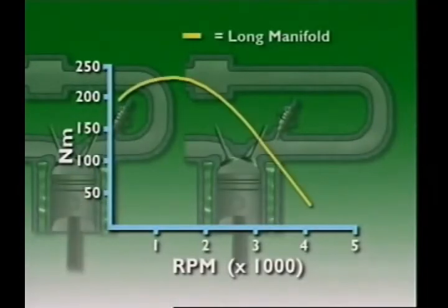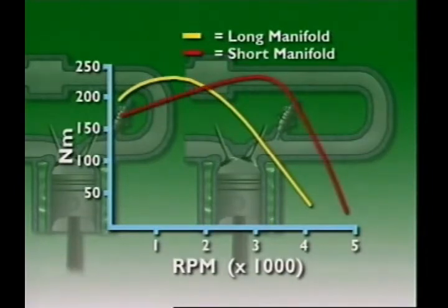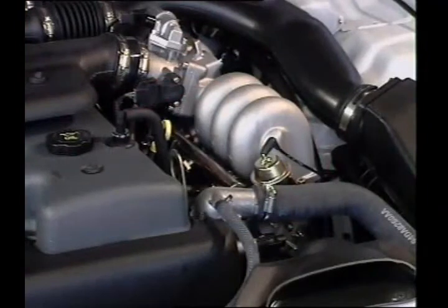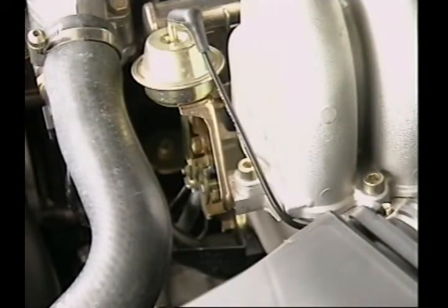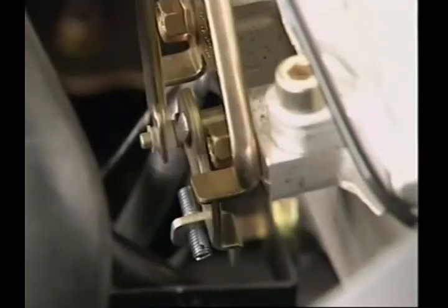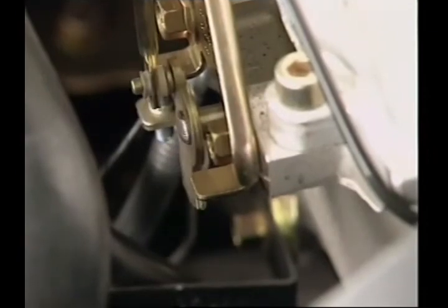In general, a long intake manifold produces high torque at lower engine RPM, and higher torque is obtained at higher engine RPM with a shorter intake manifold. Manifolds that respond to changes in engine load and speed by changing their effective length are called variable inertia or intake charging systems. They can have controlling valves operated by the engine management system, which can extend the primary type manifold into 2 or 3 stages.